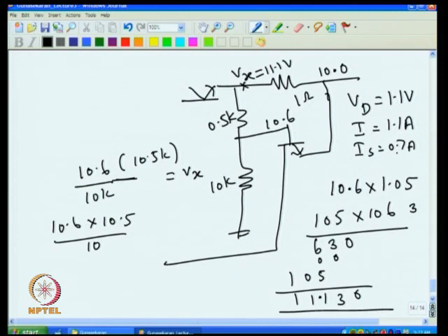So that means under short circuit condition we can limit at much lower current than what is available under normal working condition. Now this is possible because of this voltage division. If I keep this resistance larger, then even I can make this ratio much larger. For example, I can make it 1:half by selecting this resistance suitably. That you can work out and see how to select for different amount of current. So essentially by selecting these two resistance, one can get different current for short circuit and different current for normal working. This is very important.